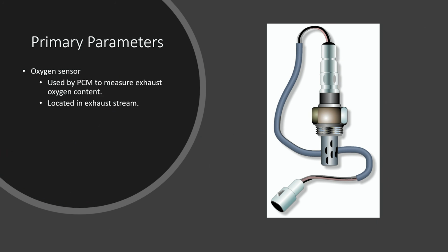So now, as we keep going on here, we have our oxygen sensor that we talked about. Remember, the big thing we wanted to make reference to on that is, I know that on the OEM side of a lot of today's cars, there's not going to be an O2 sensor reading like you maybe are accustomed to seeing. But again, if you go to the global side, you will definitely still have that 0 to 1 volt O2 sensor reading that you can actually use in your diagnostic routine.